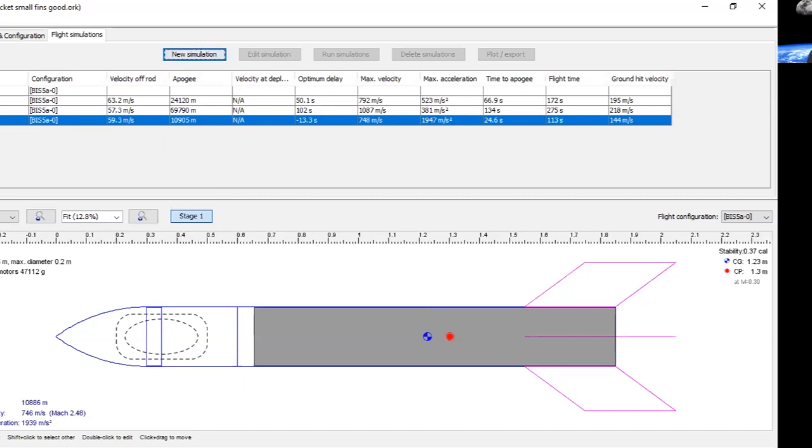What you can do to get a better model at this point is switch to another program which is similar in many ways, a program called RAS Aero 2. RAS Aero 2 is a similar program. You build the rocket from components. You've got more components, and you've got more ways. For instance, on the fins, you've only got 3 options on this one: square, rounded, or aerofoil. Well, you've got about 10 on RAS Aero 2. But what it doesn't do is give you the center of gravity position. It doesn't give you a mass calculation.